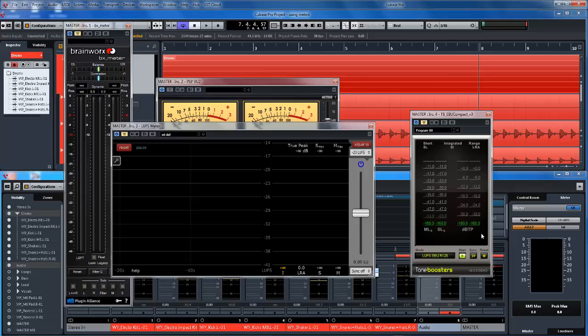You're going to wonder why we got this LKFS if it's the same as LUFS. It's really because of the BS 1770 standard and the ATSC A/85 standard. So we got the European and the international standards, ITU. They're going to vary by, I think, about 1 dB. So instead of -23, you'll get -24 LUFS.